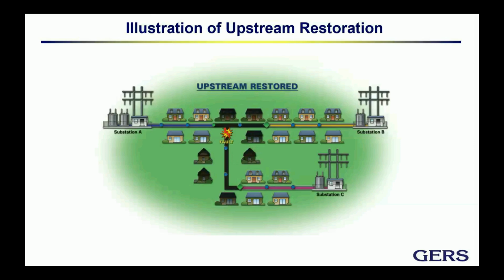So we had, with this slide, 3 different actions: fault detection, fault clearing, and fault isolation, and eventually the upstream restoration. Now, we have to do what is called the downstream restoration. And downstream restoration is the transferring of loads or users from the faulty feeder, which are still connected in healthy sections.